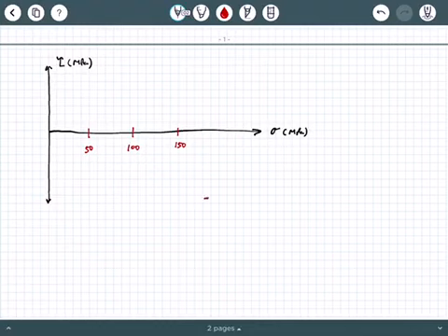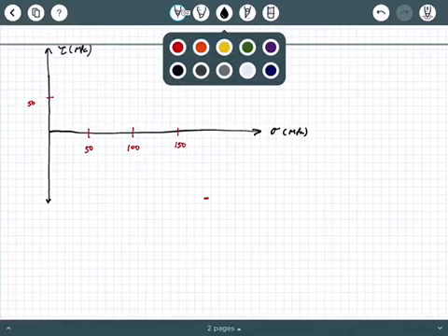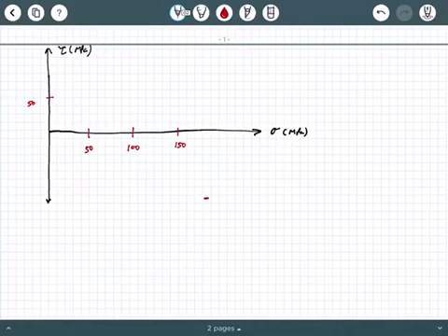And again, you want to try to draw this as much to scale as possible. So this is about 50 and this is about 100. On your own paper, you could draw it to scale better than I can on this thing. So that's kind of how I'm scaling off my sigma axis. My tau axis, I'm going to try to keep it with the same general scale. So that would be 50 right here. And then 75 would be probably 2.5 squares.